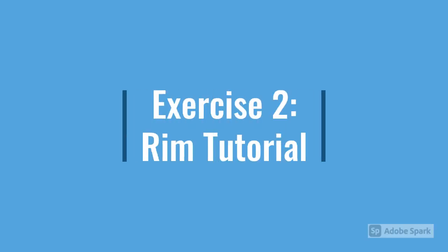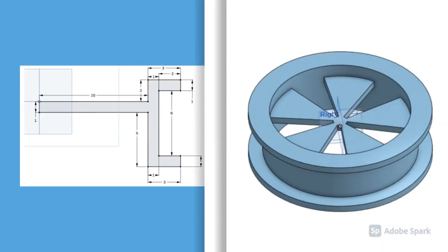Follow along with Exercise 2 to learn how you can use the Revolve tool to create a rim for a car. We'll begin by creating a 2-dimensional sketch, dimensioned like the one on the left. Then we will revolve that sketch to turn it into the rim on the right. Follow along in your own Onshape to learn how.